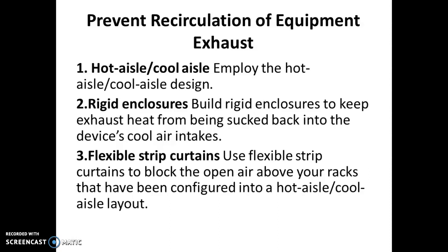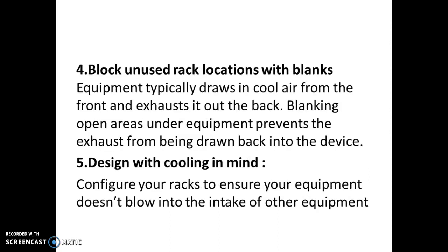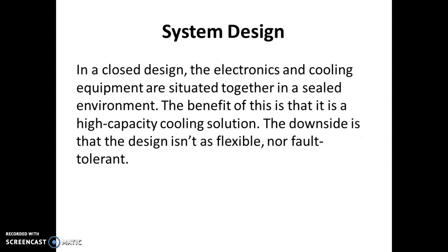We can make use of a rigid enclosure. We can make use of flexible strip curtains. While designing, we have to keep cooling in mind, so we need to block unused rack locations with blanks. Basically, the cooling requirement is an important part.